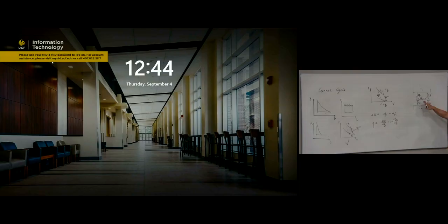But the efficiency of this one is higher than this one. Right? Then what will happen? That will be higher than this delta Q1. Delta Q1 prime will be higher than delta Q1. Exactly. Right? Correct? Then what will happen? That means we just consider them as a whole piece. We do not want to see that they have a very tiny engine inside. Then we spontaneously move energy from one part of T1 to the other part. This kind of process spontaneously happens. Right? That means one part of T1 cools down, and then the other part automatically warms up. Okay? So this is a ridiculous process, I mean, right?